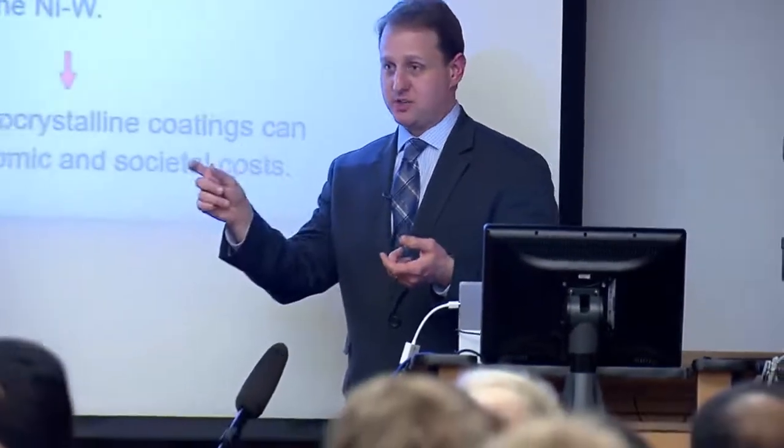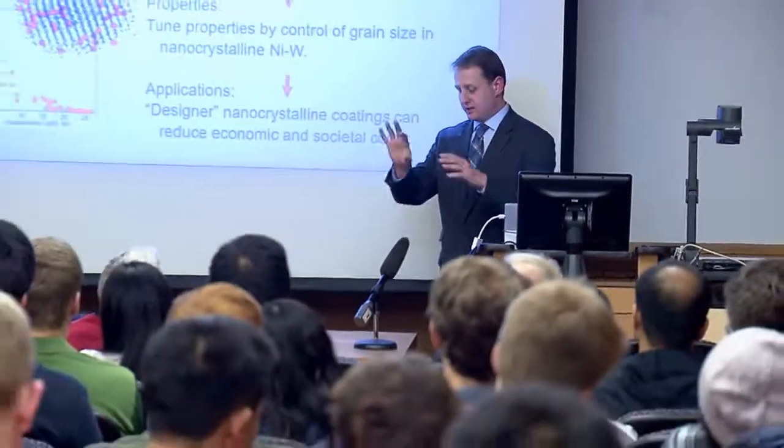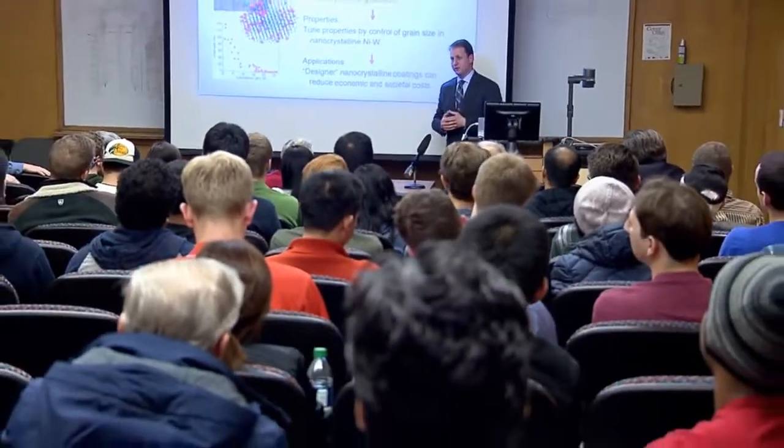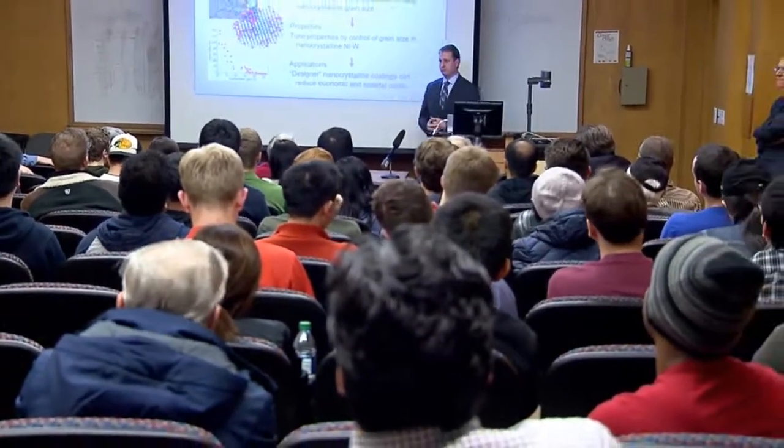How do you measure the tungsten wavelength, as you call it, in a real sample, in the TEM images that you show? It's not TEM, it's atom probe, right? The atom probe spits out a giant list of every atom, its X, Y, Z position, and its composition. So you strip out all the nickel, you have all the tungsten positions, and you just do a two-pair correlation function on that data. Boom, that's what it is.